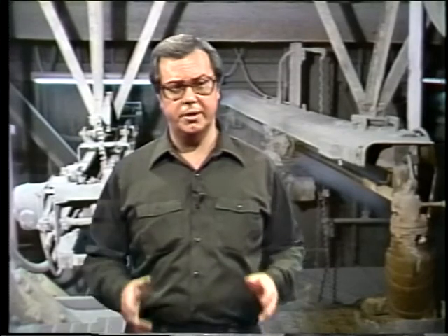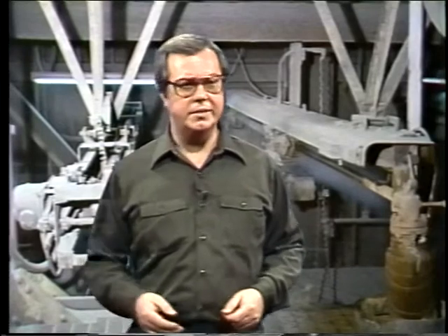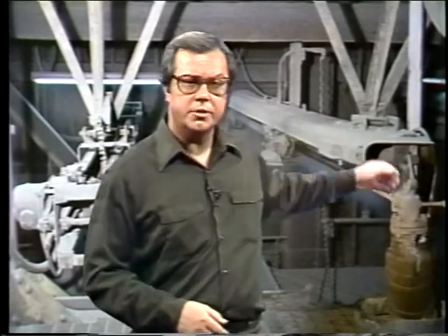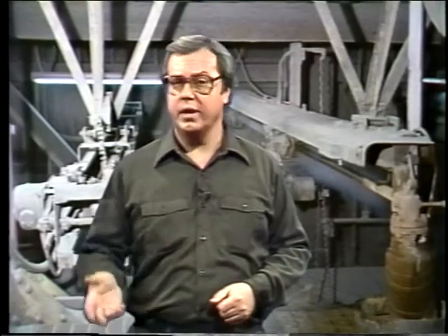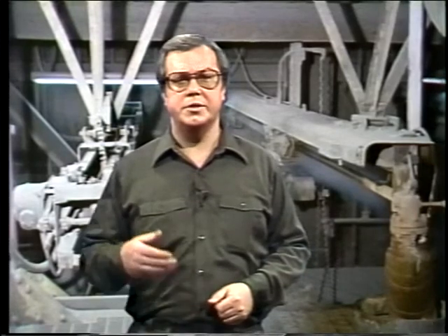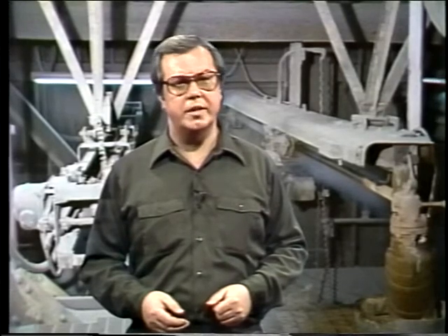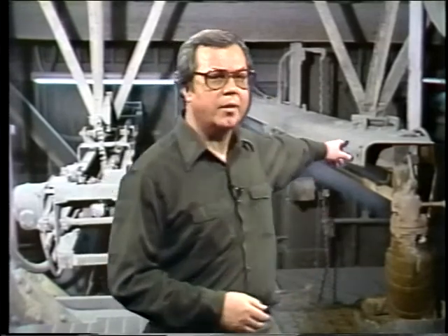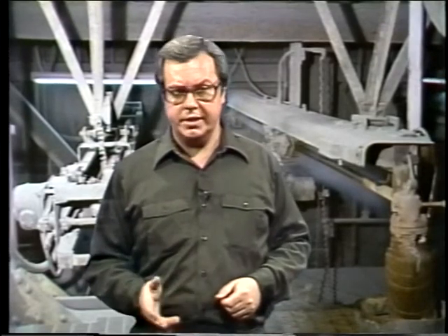Now, aside from the length of their blowing elements, or lances, the major difference between short tube and long tube retractable soot blowers is the way they're driven. The drive mechanism of a long tube retractable is virtually always powered. The drive of a short tube retractable may be power driven, or like the rotating stationary soot blower, it just may be driven by a hand wheel or a chain sheave. Also, the drive of a short tube retractable is fixed, like a rotating soot blower's drive. The drive of a long retractable travels along as the element is extended and withdrawn. Let's take a closer look at each type of drive mechanism, fixed and traveling.